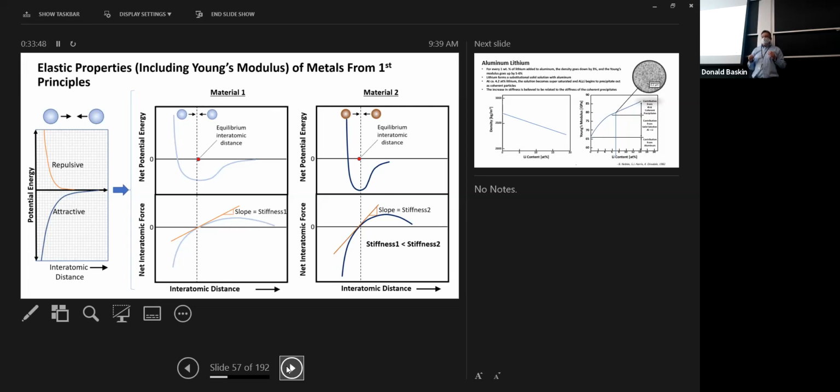All right, does this make sense? The point I'm showing you is that when you're designing a part, when you're dimensioning the thickness or the width of a part, the dimensions of a part, oftentimes in the design, you will meet your strength requirements before you meet your stiffness requirements.